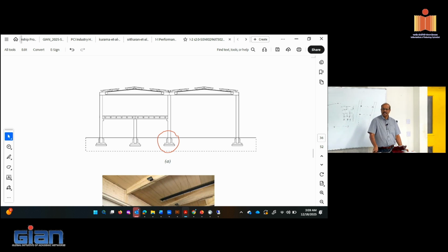There have been a lot of tests done in recent times, mostly for bridge applications. And what we found is that typically they actually perform pretty well. But in this case, it depends on what this element is made out of. So if the socket is in a foundation block, and if you can make sure there is adequate embedment into the socket, it actually performs pretty well. If it obviously is subjected to tension, you need to provide some ties into the foundation block as well.